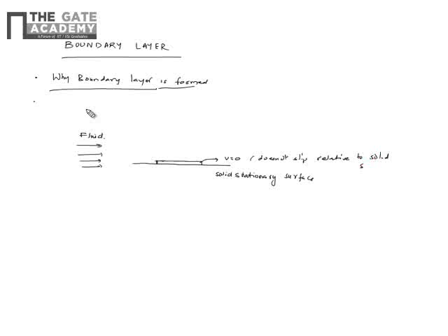You can say it's an experimentally verified condition, it has come from experiment, the no slip condition. Whenever a fluid layer passes over the solid, the immediate layer which is in contact with the solid becomes motionless. It doesn't have any velocity. So that is your no slip condition. The first layer, the immediate layer in contact, has a velocity of 0.